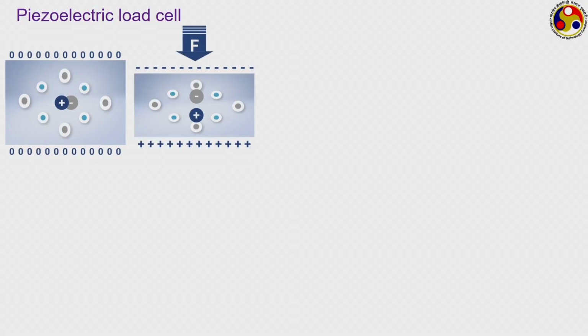These are classical devices, age-old devices; this is something much more modern. The principle of piezoelectricity we have briefly touched upon while we talked about displacement measurement, the same principle coming back here. There are certain natural crystals and certain artificial materials which, when subjected to some kind of force, produce certain charge. Without going into too much detail, initially the positive and negative ions are uniformly distributed over the entire crystal body, but when they are subjected to certain kind of stress, compressive or tensile, certain kind of force or pressure, then they distribute themselves such that one side develops a net negative potential, the other side develops a net positive potential, and thereby it is possible to get some kind of flow of charge